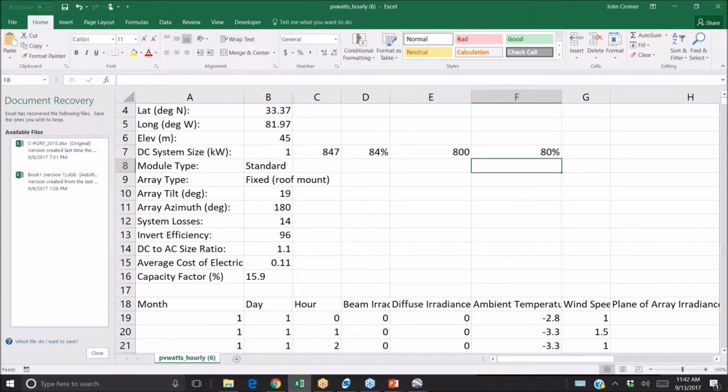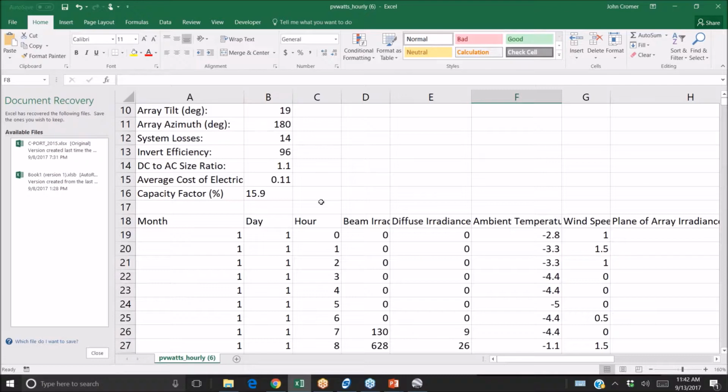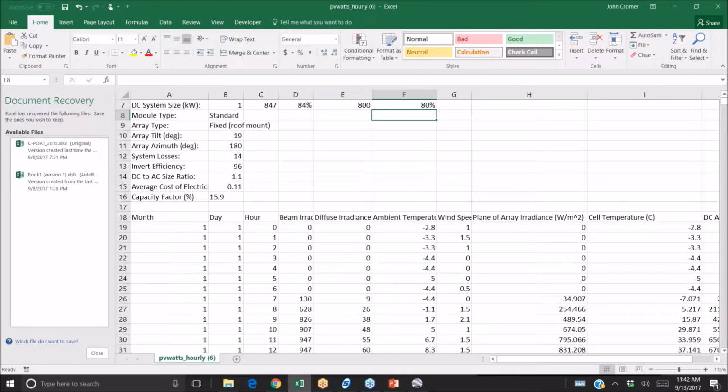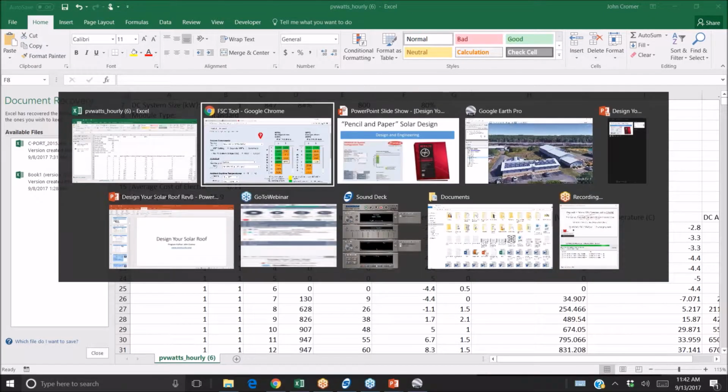And there's a number of reasons to do that. Solar modules are cheap, relatively speaking. Solar modules degrade over time. So if you're a little bit oversized today, a few years into the array, you might not be losing any energy at all. Is it bad to have an undersized array on an oversized inverter? Not really. You might even get longer inverter life out of it. It's just to efficiently use your equipment, you're in that kind of 20% range.